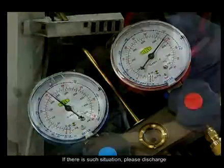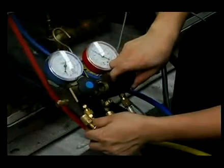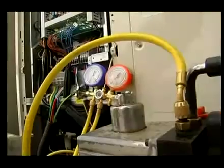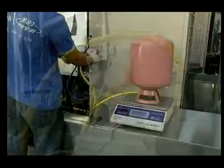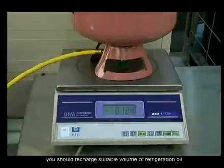If there is such a situation, please discharge all the refrigerant of the system and vacuum again. Recharge the refrigerant after it has reached the vacuum requirement. If refrigeration oil goes out during the process, you should recharge a suitable volume of refrigeration oil.